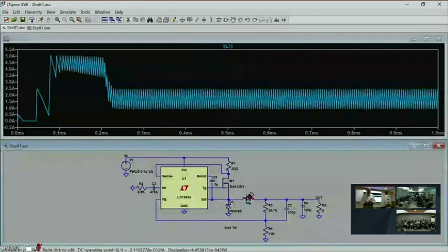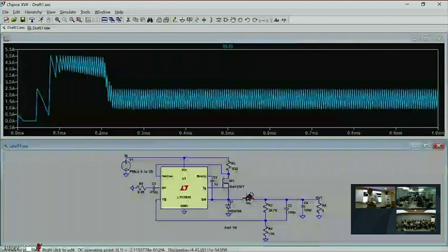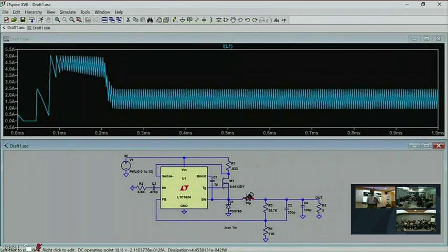So constant frequency is desirable, and this is advertised to be constant frequency, but when you look at the startup transient analysis, you see that it may well be advertised as constant frequency, but it, in fact, is not constant frequency, because when you first turn this power supply on, you'll see that it is switching at the wrong frequency, at a much lower frequency. Okay? Now, that low frequency behavior here, that's actually a desirable characteristic of the switcher. That characteristic is frequency foldback.